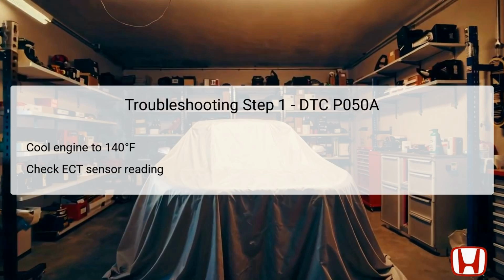The first troubleshooting step for addressing the DTC P050A is to ensure that the engine is cooled down to an ambient engine coolant temperature of 140 degrees Fahrenheit or less. This step is vital as it allows for valid diagnostic readings and ensures that the cold start conditions are replicated. The engine coolant temperature, ECT sensor, provides this crucial information, which is necessary to determine the integrity of the cooling system and whether it is operating within the specified parameters.